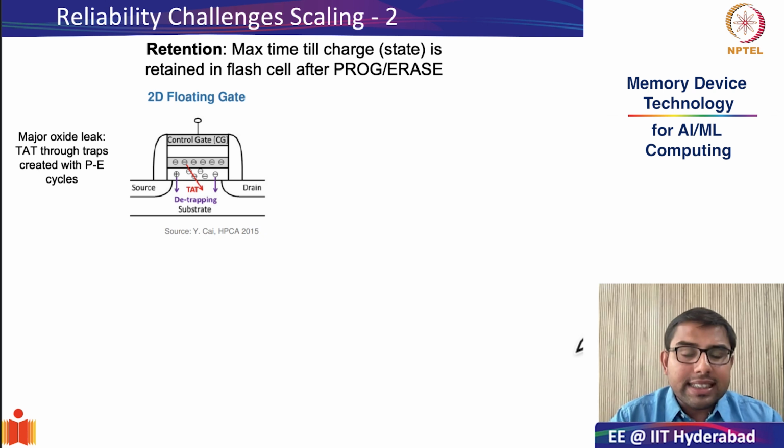As you can understand, because in a flash cell the primary mechanism of storing bits is through trapped charges, the loss of retention is also caused by the loss of electrons, just like in the DRAM storage node. When you store some electrons, there is a chance that they may dissipate out into the surrounding environment. But here it is a little bit different compared to DRAM.